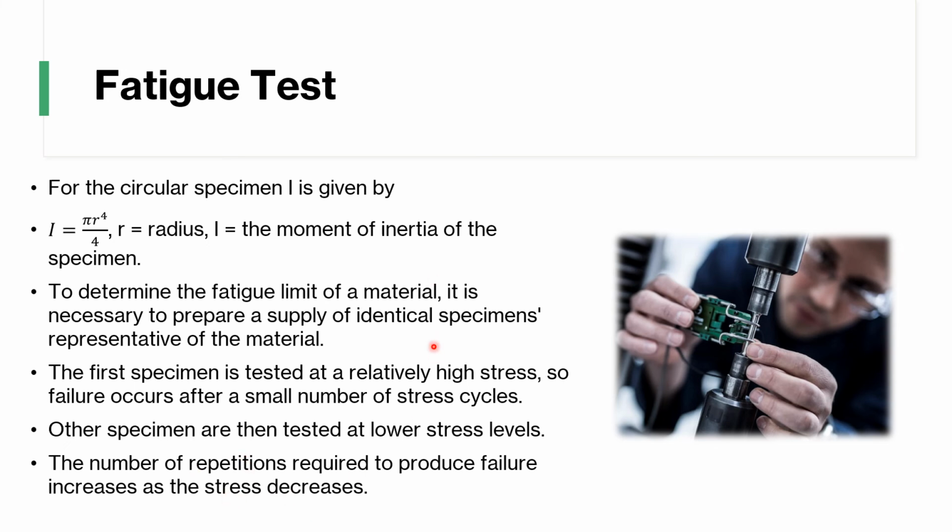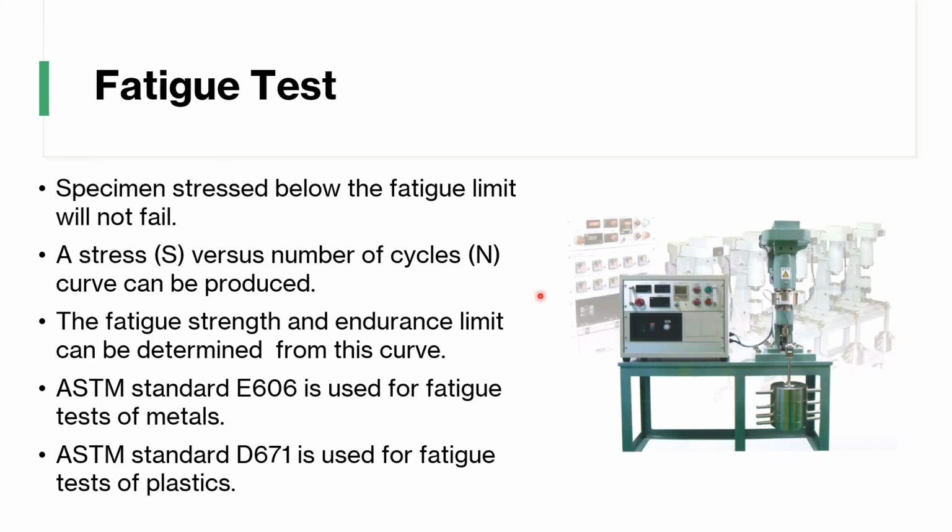If your stress is higher, the number of repetitions is going to decrease. A specimen stressed below the fatigue limit is not going to fail.